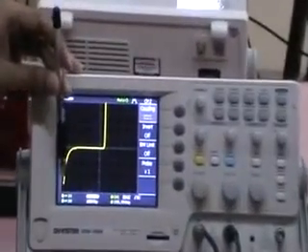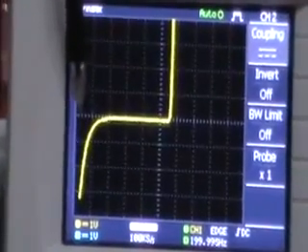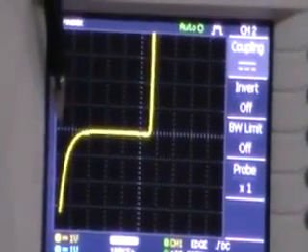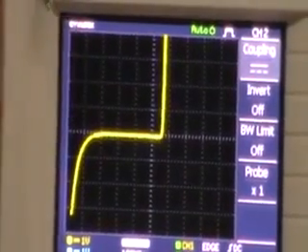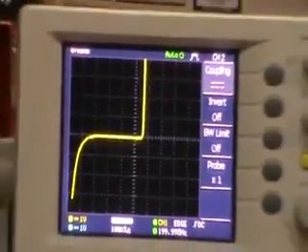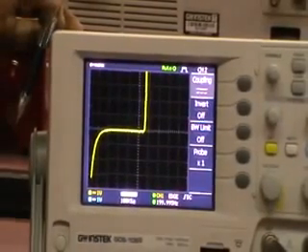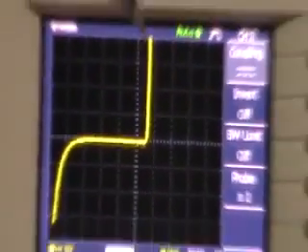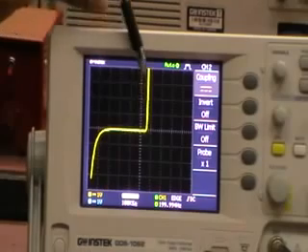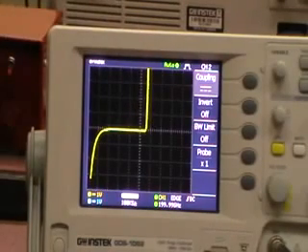We have to draw a linear tangent line along the slope line, and that voltage point on the x-axis, with voltage on the x-axis and current on the y-axis, will tell us the Zener breakdown voltage. Similarly, we find the forward knee voltage as said in the previous case. Draw a tangent along the forward characteristics, and the point where it touches the x-axis will give the forward knee voltage. So by doing this, the Zener part is completed.